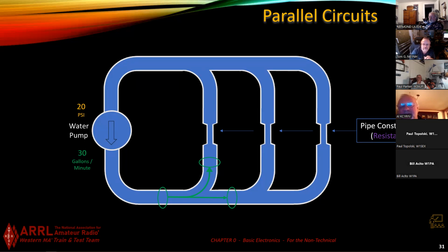So how do you do that with electricity? Think of these like valves that you close down to a certain level, because that's what your manifold in your radiant heat is. It's a set of adjustable constrictions. And you adjust them so that the same amount of water flows through each branch of your radiant heat circuit. Left to its own, it doesn't do that. Right. But this has those constrictions in it.